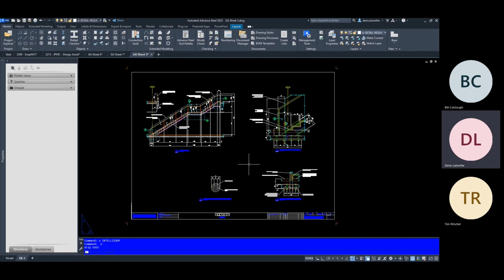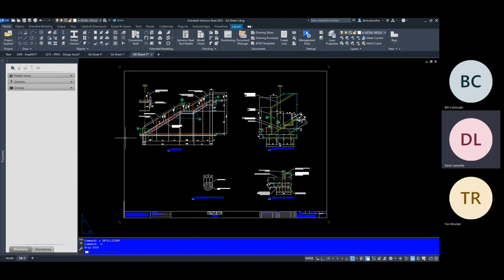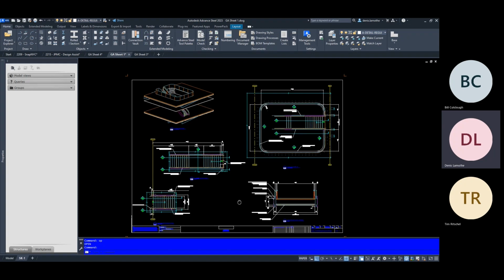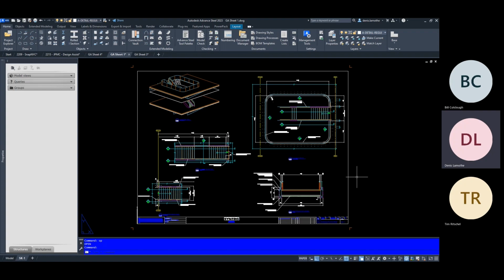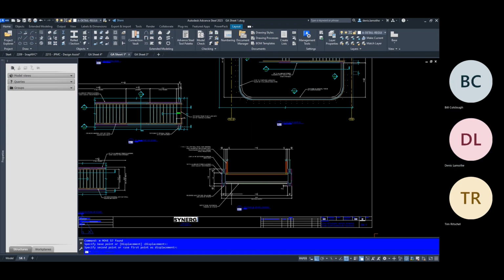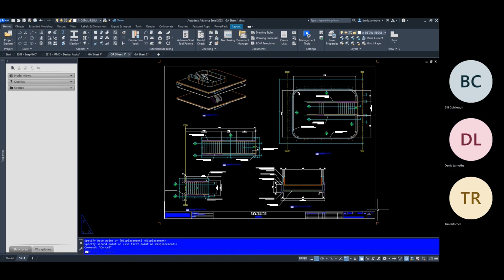Also, when you do your page layouts, if possible, try and leave a little bit of an opening somewhere on your page so that the architect or the general contractor have room to put their stamp on there to say approved as noted or revise and resubmit or whatever. There's usually 1 or 2 stamps that need to be added to a drawing. So don't overcrowd the drawing too much to the point that you don't have room to put a stamp. I'm not going to necessarily tell you it's got to be at the bottom right corner or anything like that, but just anywhere on the drawing they can fit in. Actually, I probably could have just moved that over a little bit this way and left room here.